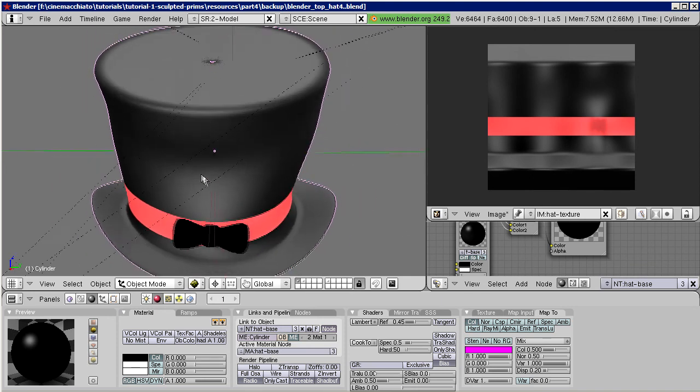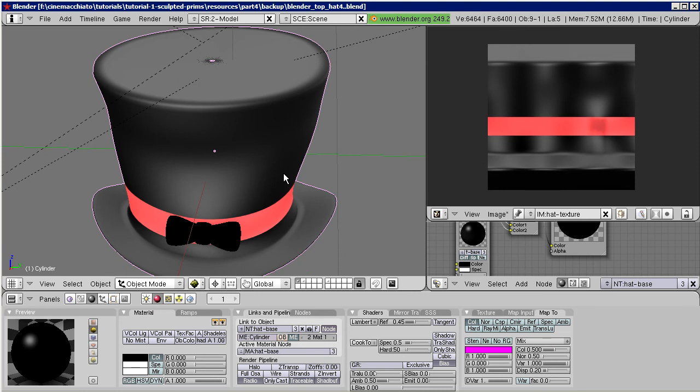The reason is that the model is using the low poly mesh, but the texture should be created with a much finer mesh and then baked to the low poly mesh. We will come to this technique later. For now we can just increase the number of subsurf levels by 1 or 2, and then full bake again.